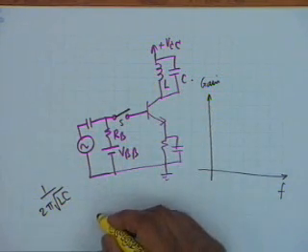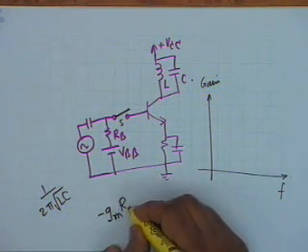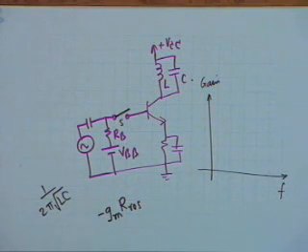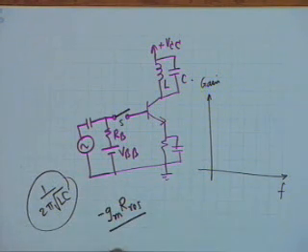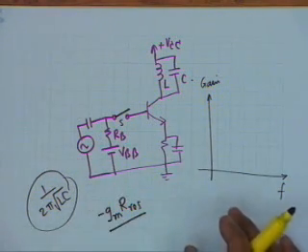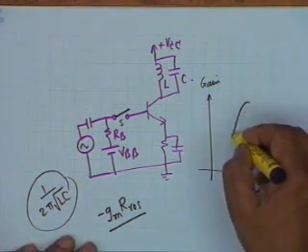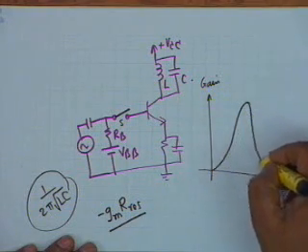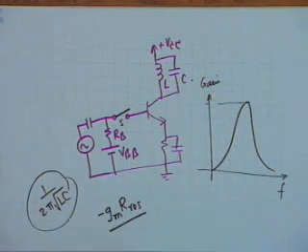But whatever the load is, you know the gain is minus GM times the effective load. So, if we say resonant resistance is R res, then the gain shall be minus GM R resonant at the frequency 1 by 2 pi square root LC. If we go away from resonance, either on the right side or on the left side, the gain shall decrease, and therefore the gain shall follow a resonance curve like this, where the maximum gain shall be minus GM times the resonant impedance.